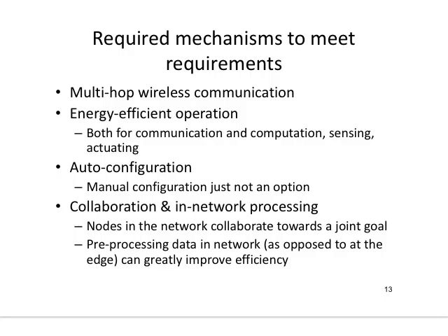So we need some real algorithms to say, okay, the temperature that I received now didn't change. So why do I need to communicate it? Okay? And then adjust the sensing frequency based on the changing frequency of this temperature. So we need algorithms to do that.